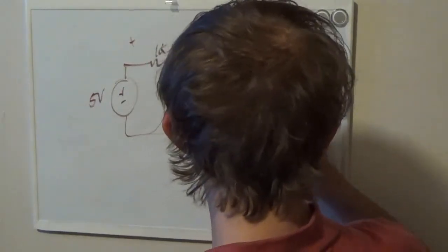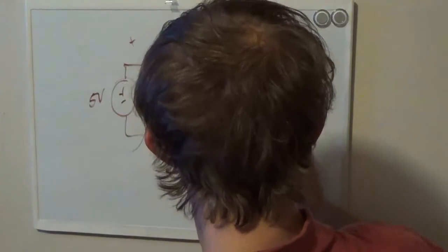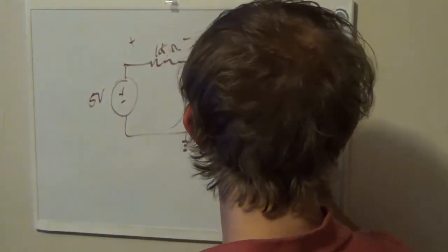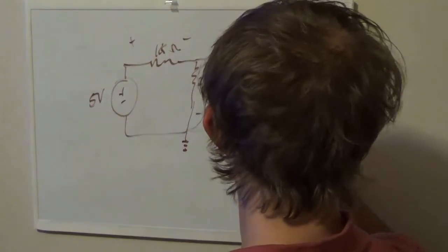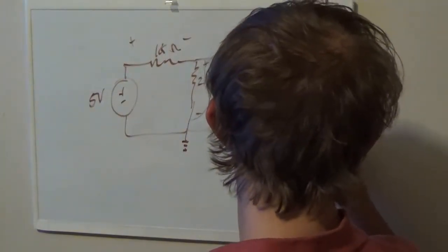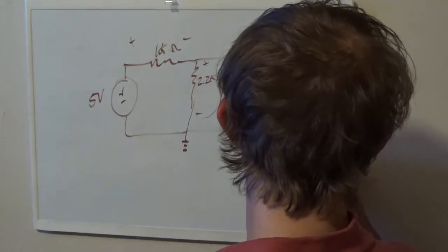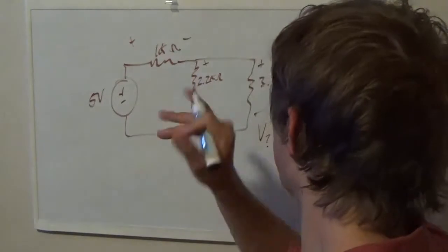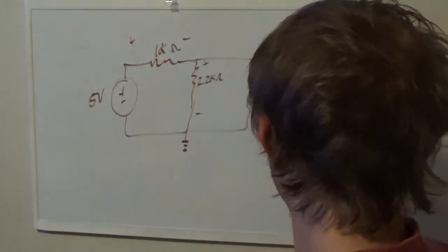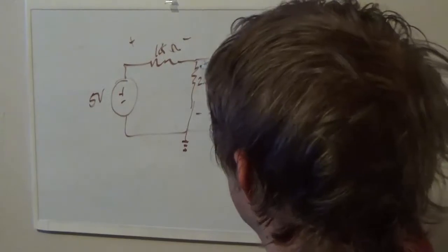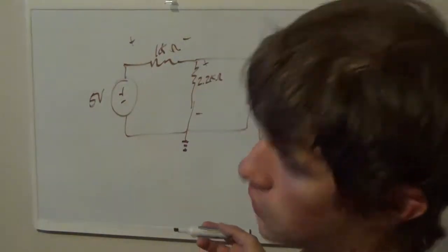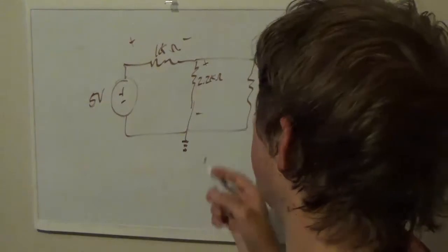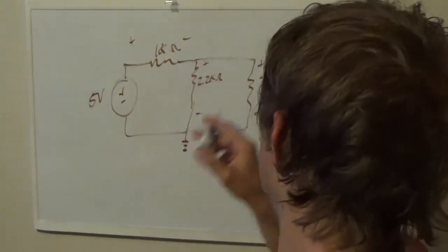So, what we're going to do is I've derived the equation for voltage division, which just so happens to be V of whatever you're testing, whatever resistor that would be, is Vs times R1 over R1 plus R2, whatever that ends up being, your equation. So we can use this equation to ultimately solve for all of the voltages, or all of the potentials even. Potential is another word for voltage. I believe I've already talked about that. At each of these, across each of these resistors.